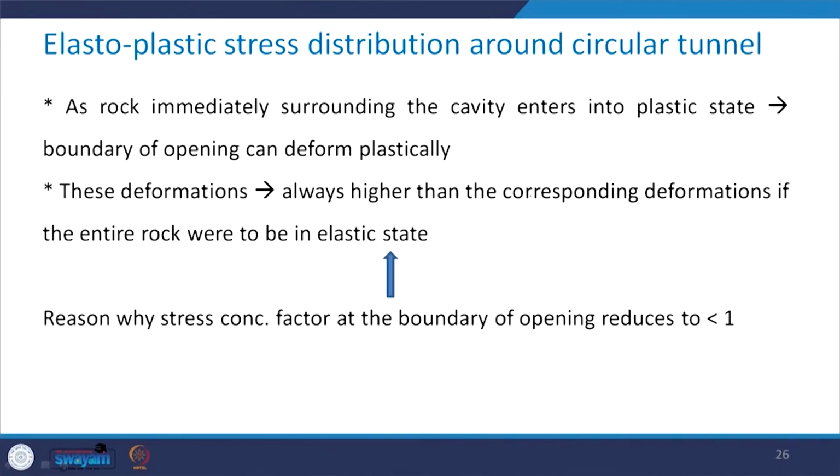Now, as the rock immediately surrounding the cavity enters the plastic state, the boundary of the opening can deform plastically. These deformations are always going to be higher than the corresponding deformations if the entire rock were in the elastic state. That is the reason why the stress concentration factor at the boundary of the opening becomes less than 1.